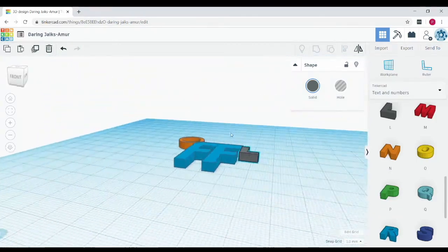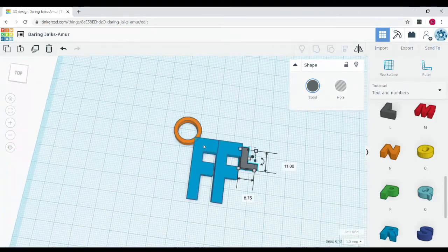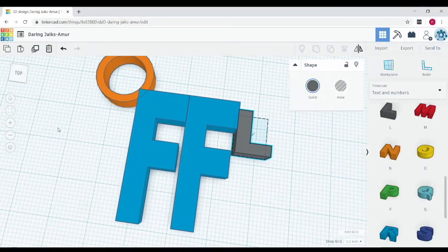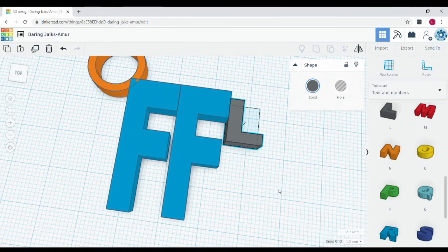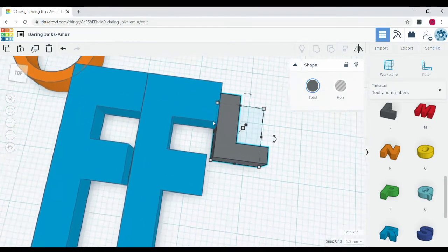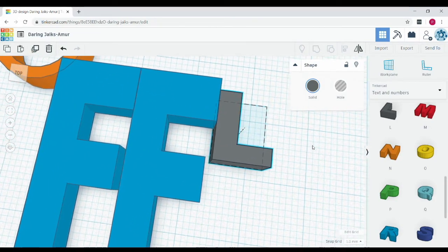So when I'm rotating around, it can be hard to see, especially if I'm zooming in on the wrong place. To change the center, I'm going to click the mouse wheel, and then I can just drag around, and that'll change the focus of the work plane. So now I can kind of zoom in nicely over here.